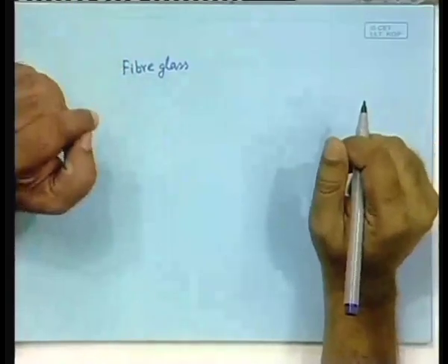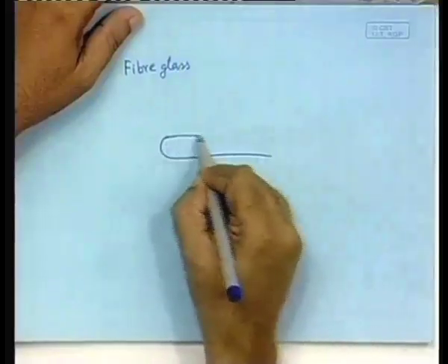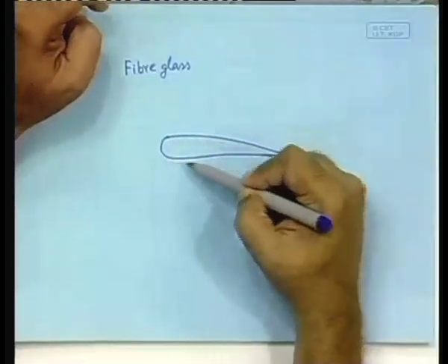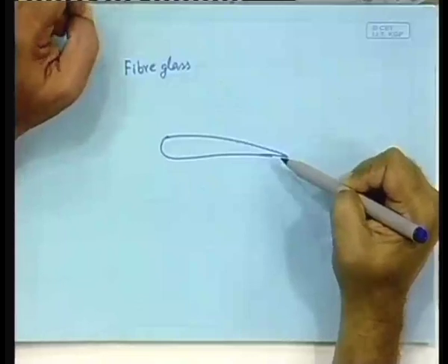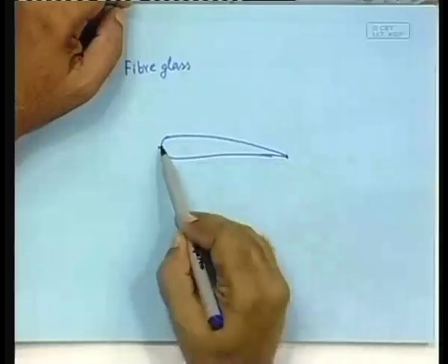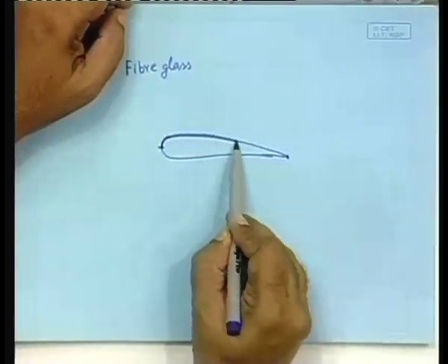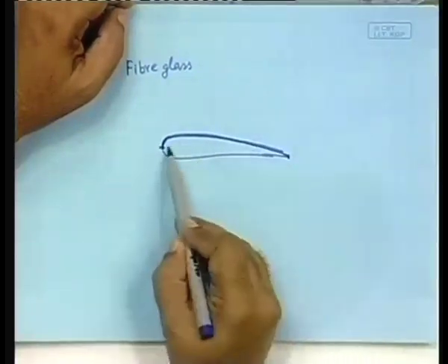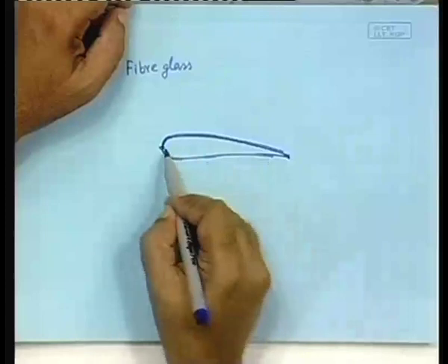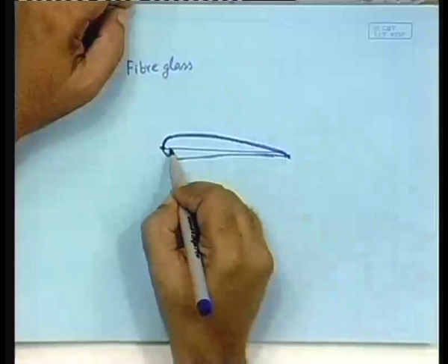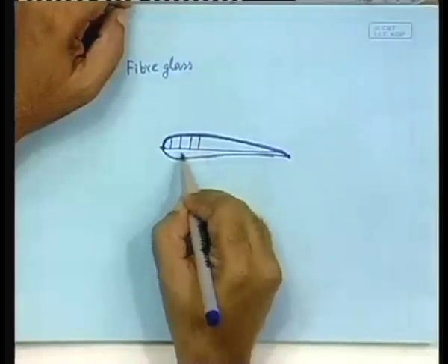What will be the section? That means, you have seen that it requires a certain section. As I told you, these sections are similar to those of the aeroplane wings, with various specific geometries. Geometry means, from here to here, what will be the exact equation or coordinate of each point in the upper layer and the lower layer. These are given in terms of, let this be the chord line, the distances and these distances.